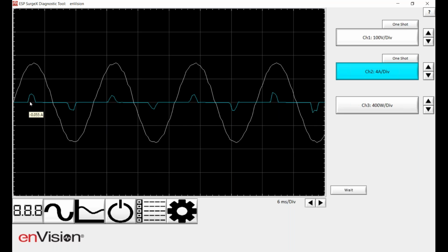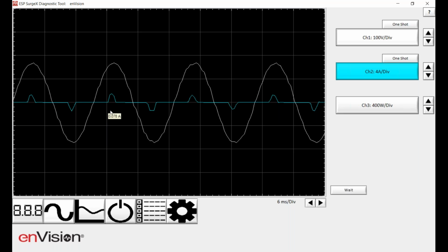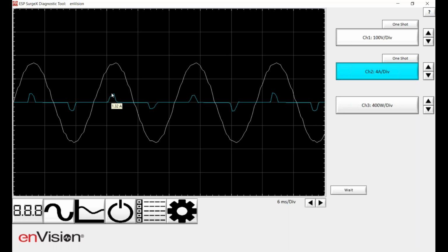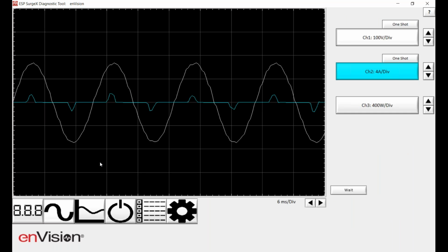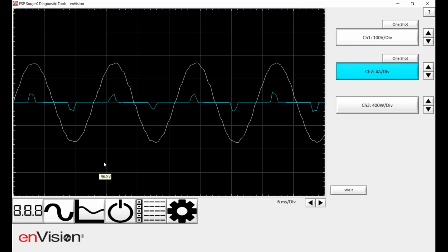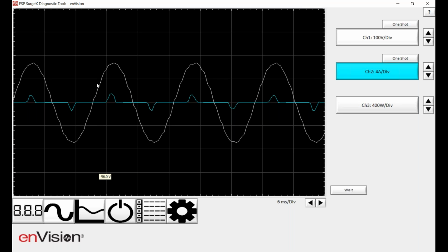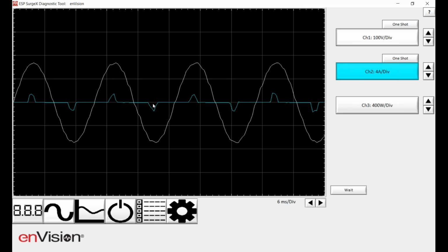So one of the things you can see here, as far as the current draw is concerned, is that the little power supply on my laptop computer does not pull current in a sinusoidal fashion like the AC voltage is. It only pulls current at the peak. So as you can imagine, if I'm pulling current only at the peak, and if I have a long wire run where I'm being restricted by when current flow happens, that could cause the top of this waveform to get chopped off. Only at the top. It's not like the whole waveform is reduced in amplitude. It's just the top gets chopped off. And when you get that chopping off, that's when your crest factor will go down to the 1.3s and the 1.2s. So again, this is a numerical representation, and you can see it. So what can you do if you've got that? Well, if you've got a low crest factor, that's an indication that the wire size may be small, and that you've got these kind of impulse type loads.